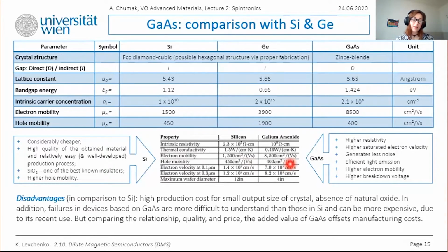Also, gallium arsenide doesn't have a natural oxide. You have to perform some chemical vapor deposition to get the oxide or the nitride insulating layer on top of the gallium arsenide. And even through this complicated process, the achieved oxide will have poor quality compared to silicon oxide, and it won't stick nearly as well, leading to manufacturing defects. So gallium arsenide is not the best candidate for the MOSFET.